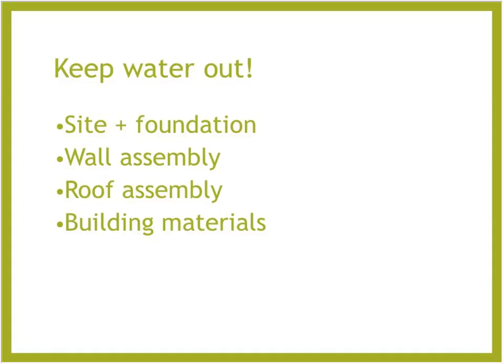Roof assembly: roof leaks occur all the time, sometimes because of things out of our control, but other times because of failures in the roof and failures in the design, failure in the builder to put the shingles on correctly and not having anyone check that, all the way to using proper sealants and flashing around the roof and where the edges and pitches come together. All of those help keep water out, to flat roofs that have failing membranes.